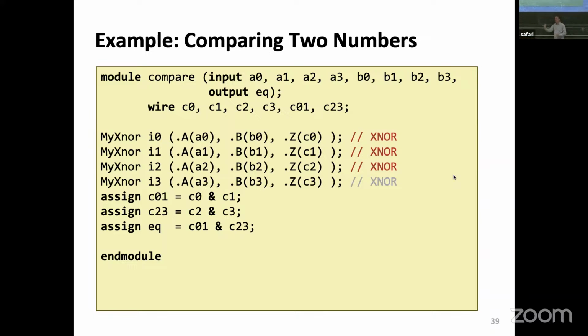We could have designed a hardware that does it in steps. We will do that, but we don't have the knowledge yet, where we process this in sequence. We say, let's first take one bit, and if that one bit works, let's go to the next one, the next one, and if not, let's terminate early. But that requires a bit of memory. We have to say, I will do it in 4 steps, 5 steps, whatever, and at every step I will do this and continue, or else branch out. We will call that finite state machines, and we will discuss it later.